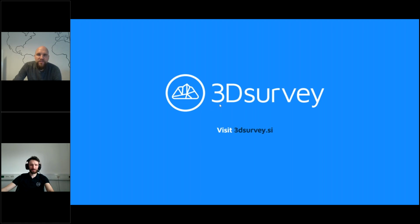So the second question. Some of these are already answered. But there was a question: are the measurements in centimeters or in meters? By default, if 3Dsurvey is set to the metric system, all measurements are in meters. But then I just look at the last digits. So if it says 0.07, that means 7 centimeters.